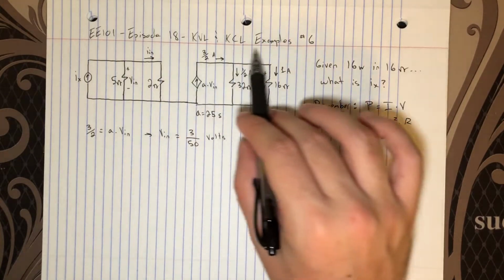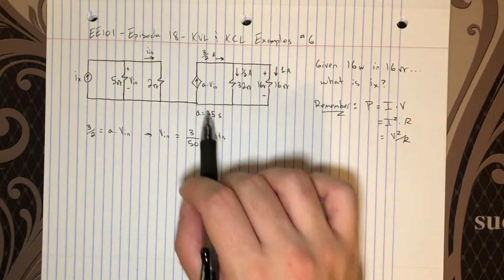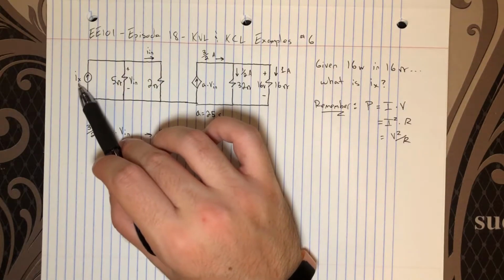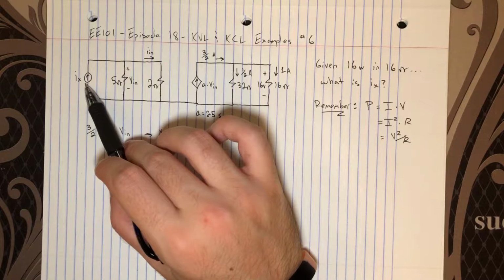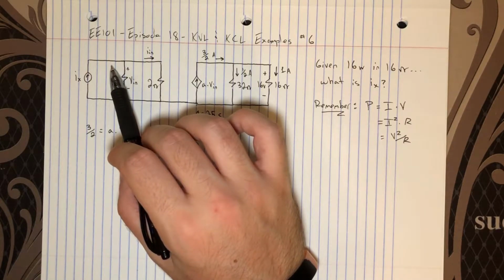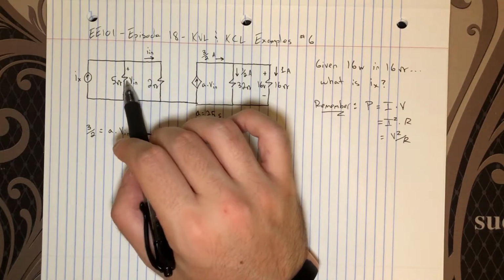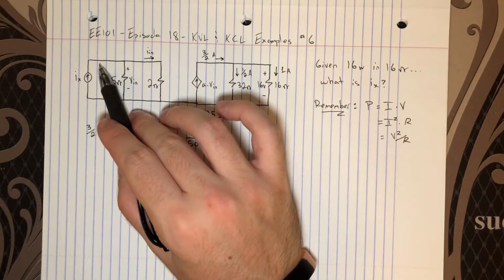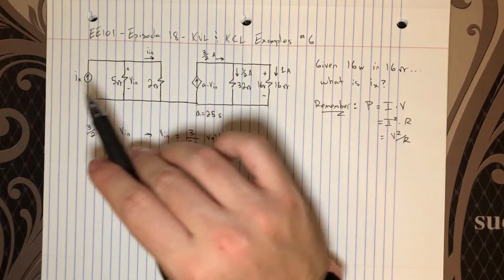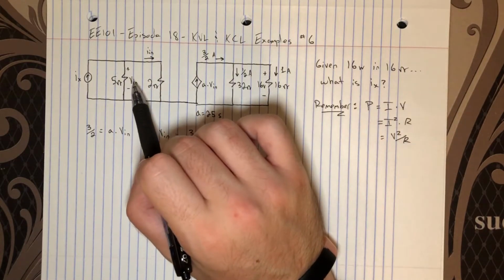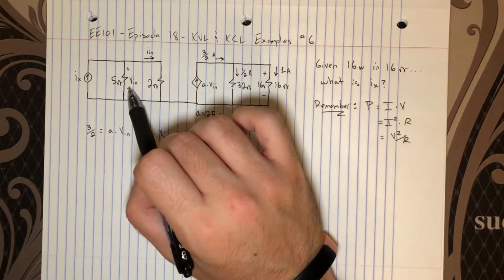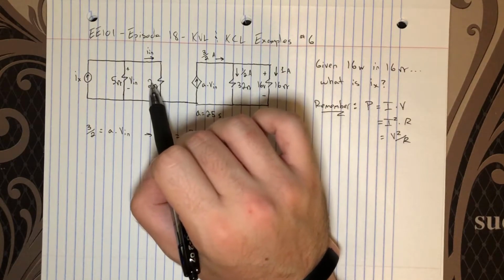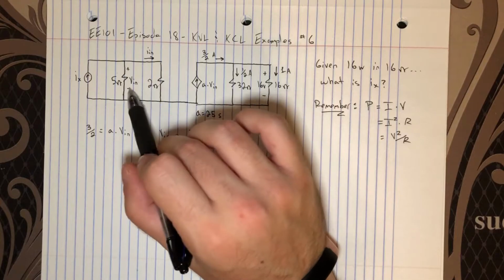Now look back over here. We have total information about the right half of the circuit, and now we've just learned Vn. And ultimately we want Ix, so I think it's in our best interests to solve for the currents in these two resistors, and then a KCL will give us a quick answer. Given that we know Vn, we automatically know the other voltage, because again these two resistors are in parallel, so you see Vn across them both.